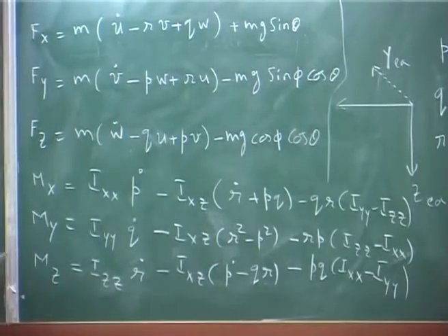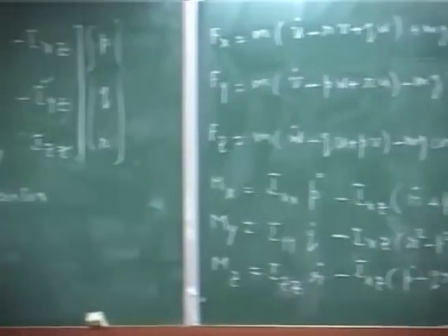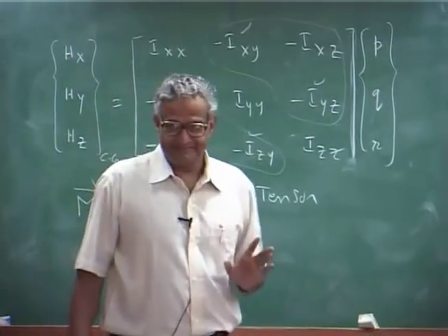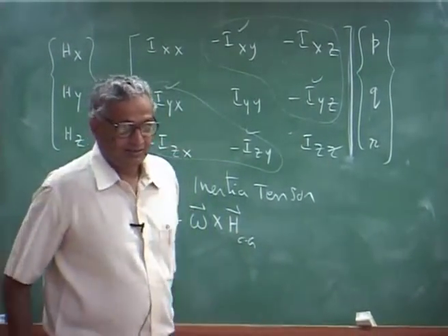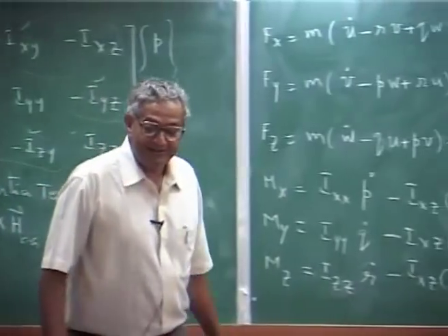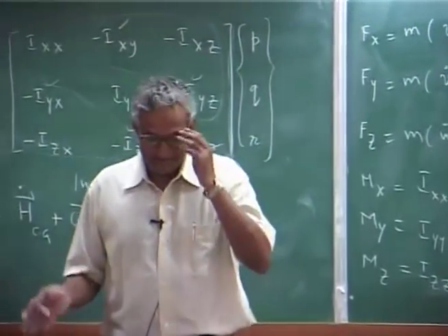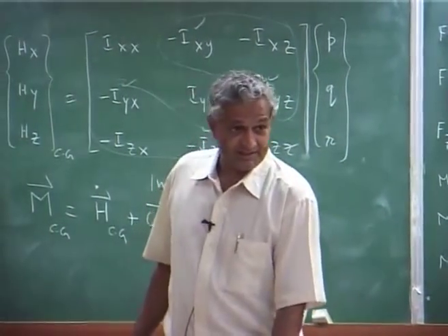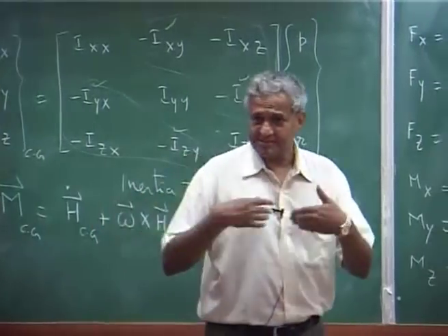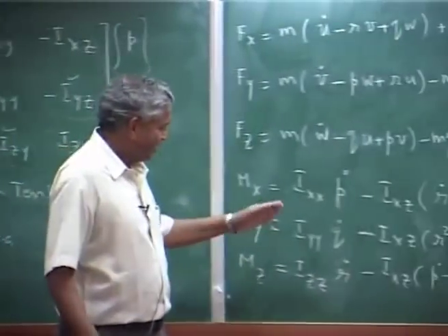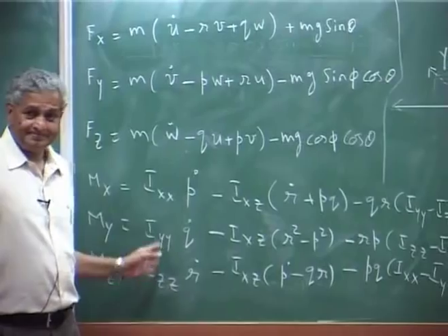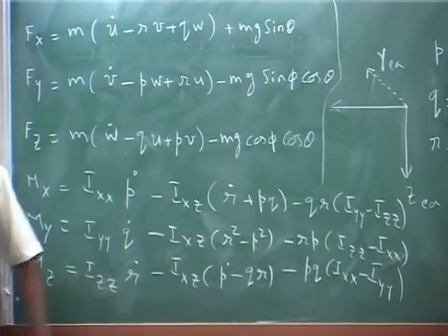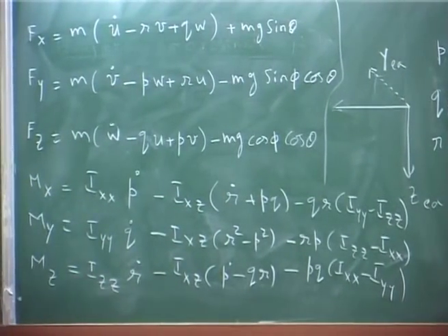Okay. These are my equations, and normally you see Ixz is comparable to Ixx magnitude wise. That is why the weights and CG group in any aircraft or aerospace company has to get these values before the aircraft is built.